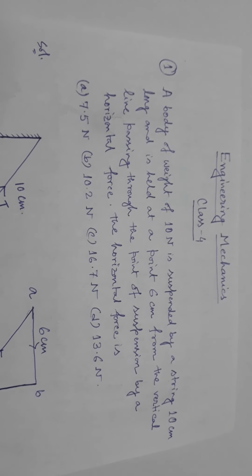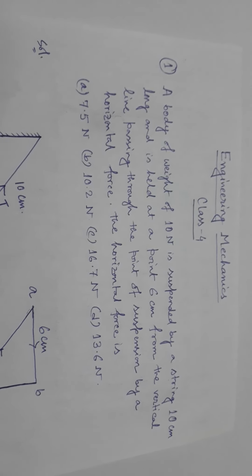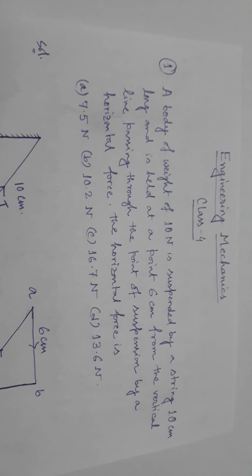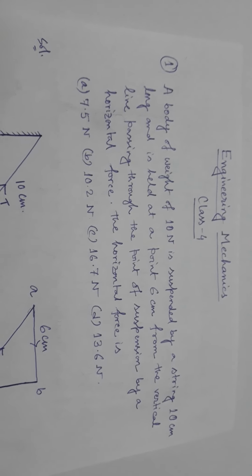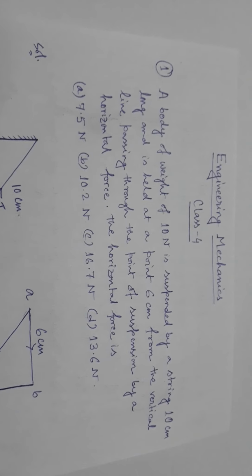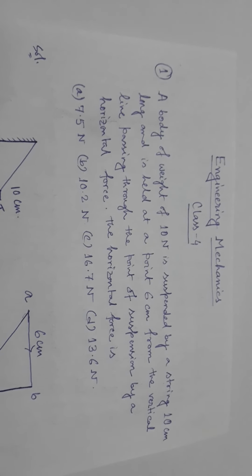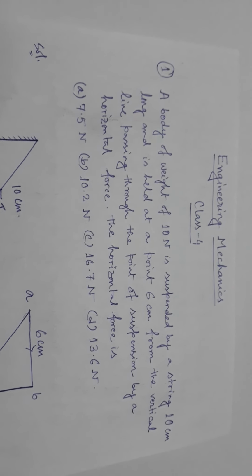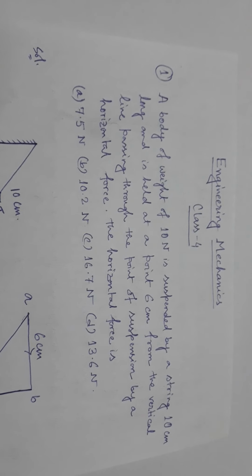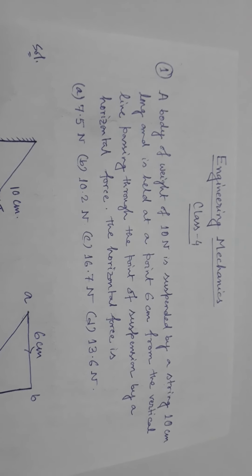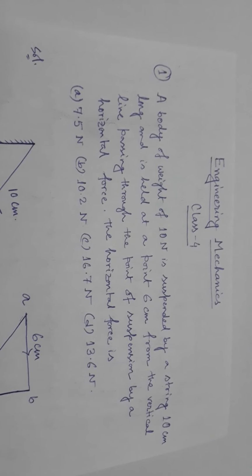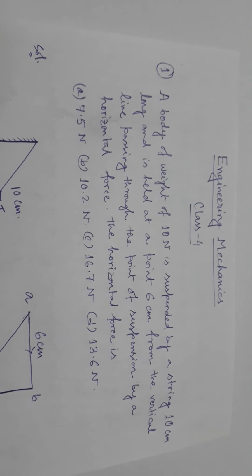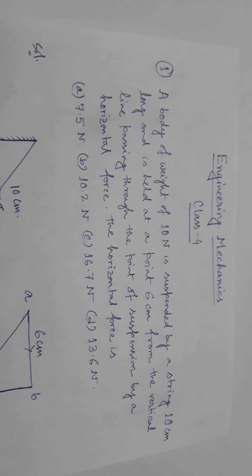In my first three problems, the systems described are in equilibrium, and as such the lines of action of all the external forces must be concurrent, that is, meet. The solution is then obtained by drawing the free body diagram for the system and the corresponding force polygon. So let's focus on the first problem.